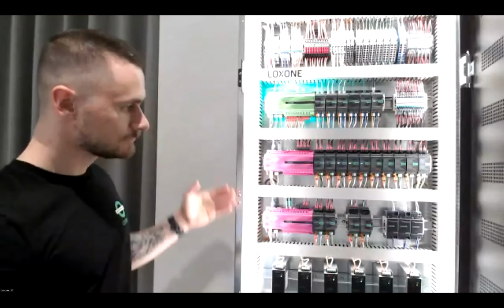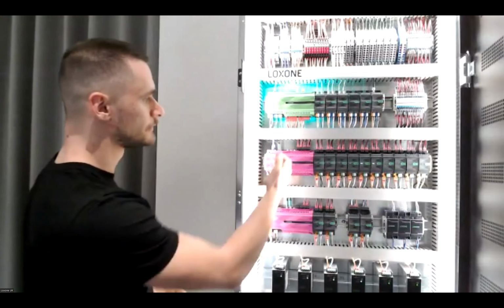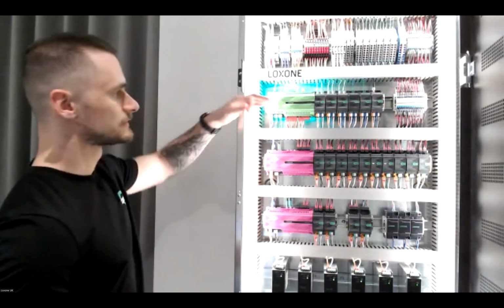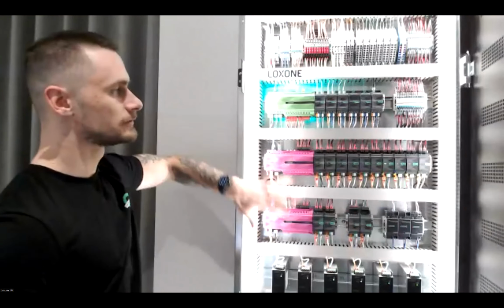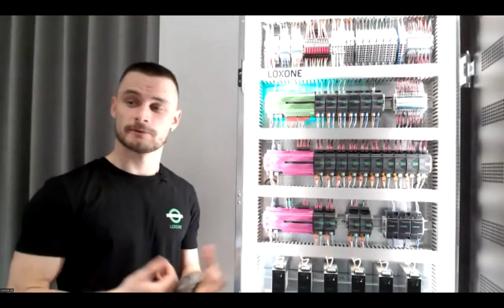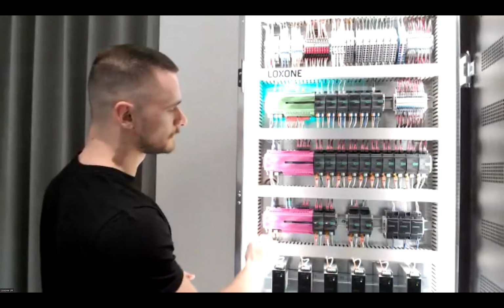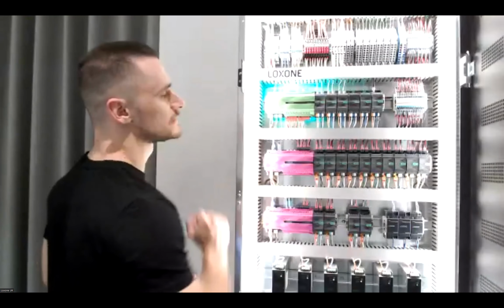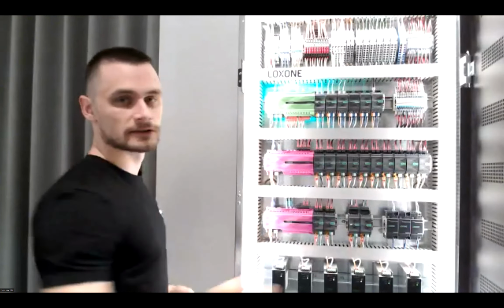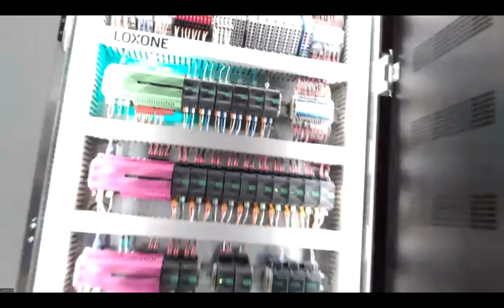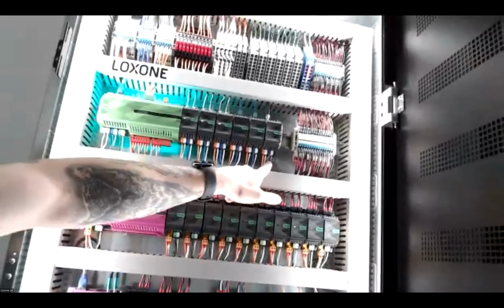Now, obviously, you can have the separation between the mini server and devices and the audio server. That's absolutely fine. I'll actually recommend doing it this way. However, if you start going up the panel, you can see, okay, mini servers here, extension here. The very, very last extension does have a 120 ohm resistor. I don't know if you can see. There we go. Which you should always have at end of line.